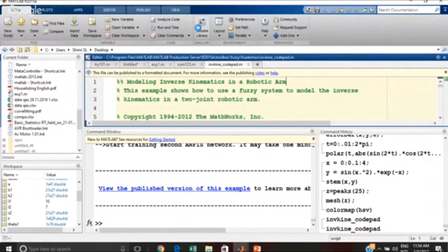Whenever you want some blocks, you just drag them from there, put them into your system and reconnect them. I'll be showing you step by step, but for learning Simulink there are some basics. You have to know a few things so that Simulink will be very clear. One of the things is making a subsystem. Say you have a very big system, a motor control system. In that, first you have to make a motor.